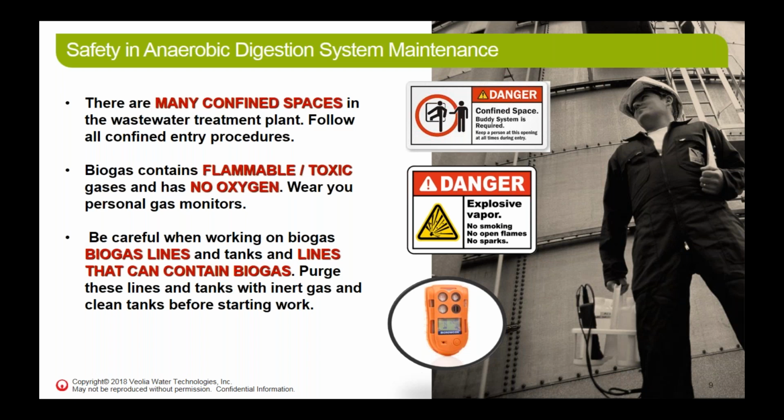And also looking at biogas, you're not only talking about the reactor itself, you're talking about biogas pipelines. We do have flanges on biogas pipelines. Over time, maybe the gaskets start to get old, they leak a little bit, so you can have gas there. You should always carry your H2S and your LEL safety detectors. If you don't have them, you can talk with Jill Jordan after the webinar to look. We recommend that all operators, while on site, carry this. It can clip on to your belt. It will detect methane. It will detect H2S.